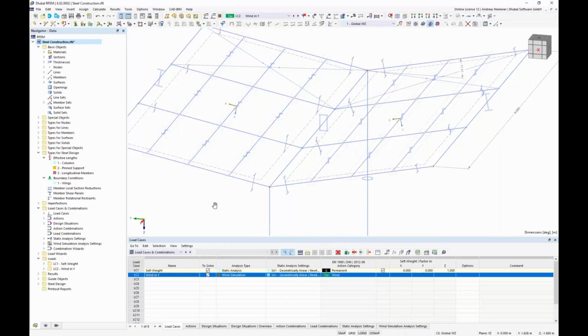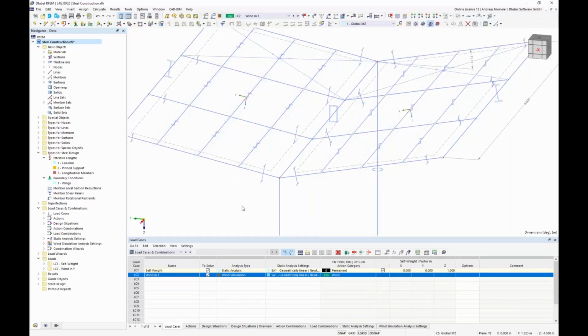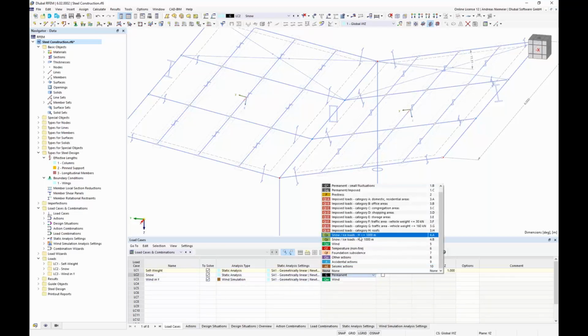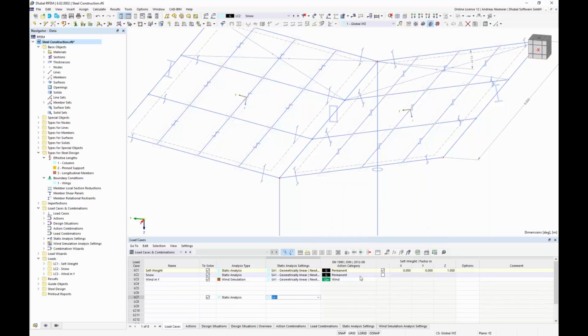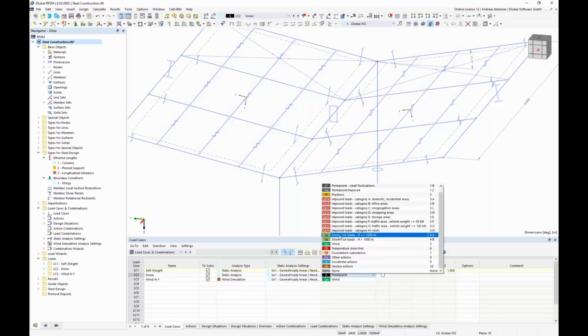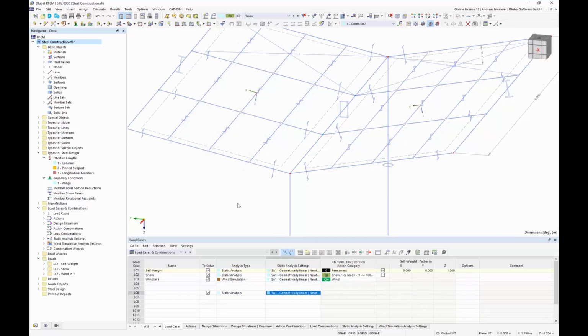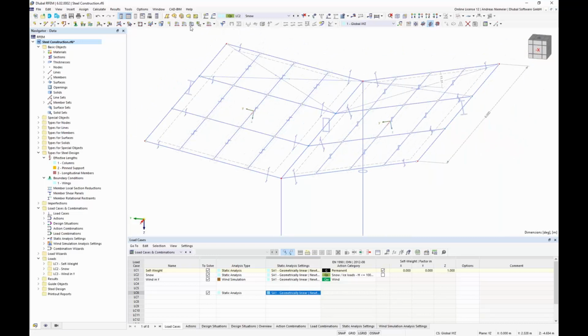Then let's take a look at the power of the surfaces itself. For this, we move this load case 2 to 3 and make here a gap. And we say, okay, we place here, for example, a snow load, and give here action category snow. Okay. Now let's define some snow load to show how this surface is acting.